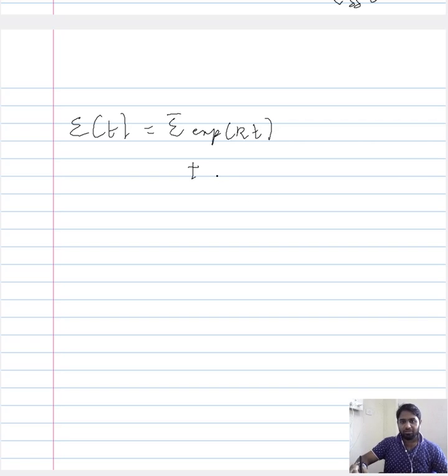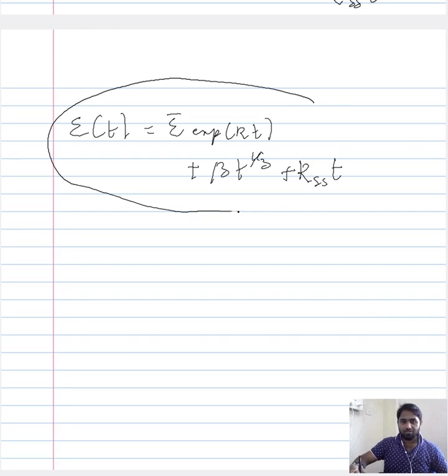The second term talks about the decelerating strain by including a prefactor and relating the time in this form. And finally, you have a steady state condition wherein the strain rate is more or less constant, and a definite amount of strain for a particular period of time is expressed by this constant here. When you multiply that with the overall time during which the steady state condition is exhibited, you will be able to ascertain the amount of strain during that period. So this is how the first expression that represents the overall creep curve looks like.